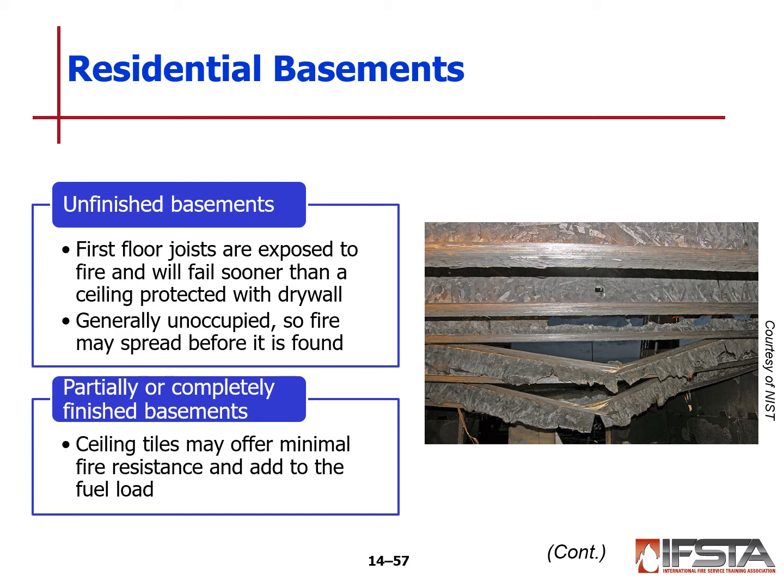Unfinished basements. In our residential homes, the first floor joists are exposed to the fire and can fail sooner than a ceiling that would be protected with drywall. Right now, in my house, it is unfinished. Some people will go ahead and put sheetrock or drywall onto the ceiling and cover it with a 5/8 thicker sheetrock, and this would certainly keep this from happening, or extends that period of time, if you will. Generally unoccupied, so fire may spread before it is found.